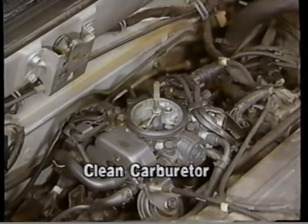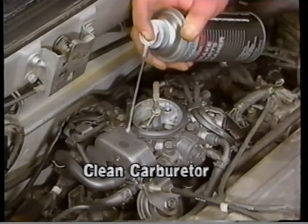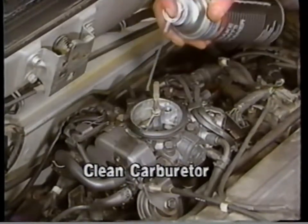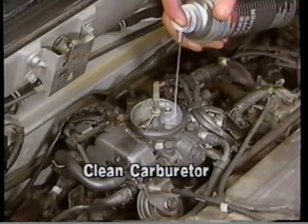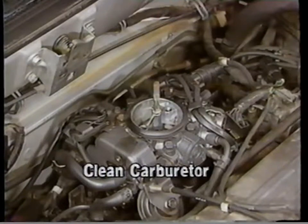Next, clean the outside of the carburetor and the choke linkage with Mopar brake and carburetor parts cleaner, part number 4318037 or equivalent. Also, clean the primary air bleed jet, the secondary air bleed jet, and the choke shaft.